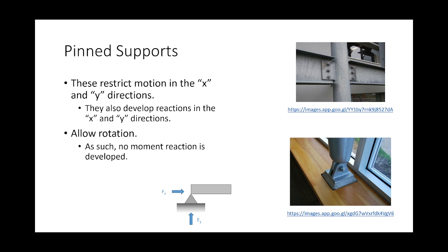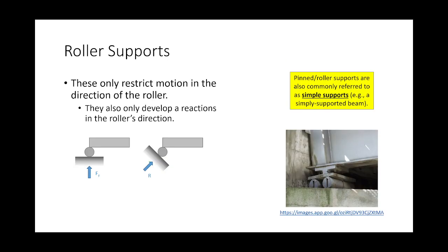So whenever you see a steel frame building, if the flanges are connected, that'll transmit moment. If not, it'll only transmit forces. Okay, another common example of a boundary condition is what I call roller support.